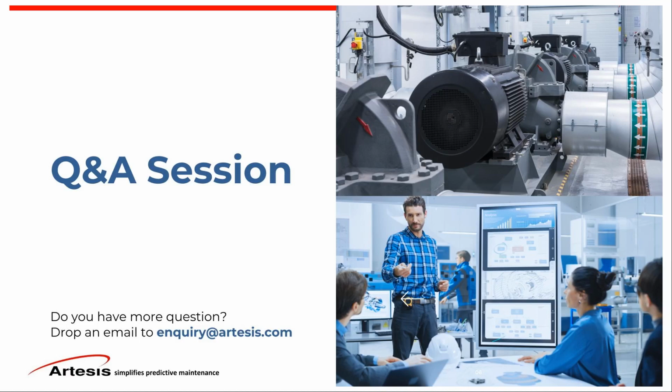Can we schedule the frequency of data collection? Yes, you can change the settings on the software. Again, that was a previously asked question, so Pravin asks this. Yes, you can change that, and you can make it as low as 1.5 minutes. In case of a major overhaul or rewinding of the motor, you have to relearn the motor, because that changes the characteristics and the behavior of the motor. It needs to be relearned.